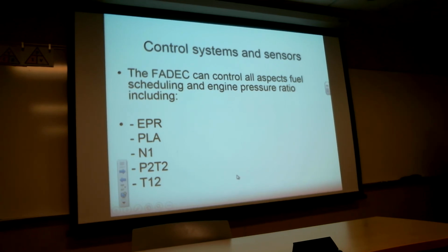So let's go back to Phoenix. It's pretty hot, but you're within the performance parameters of the engine. What's going to happen? So the temperature is going to be pretty high. What's the air density going to be? Pretty low, right? So the aircraft is going to think it's already at 10,000 feet because of the density altitude, even though it's sitting at the elevation in Phoenix. So would we give it the same amount of fuel as if it was sitting here in San Diego at sea level? No. And so what's that going to do to the performance of that engine? Because we're going to give it less fuel, it's going to make less power.